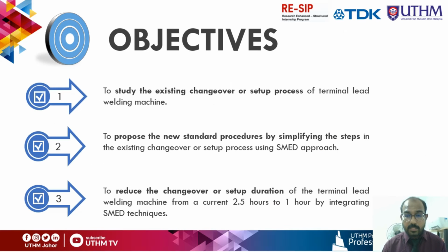The objective of my case study is to study the existing changeover or setup process of the terminal welding machine. My second objective is to propose a new standard procedure by simplifying the steps, the main activities that I showed before, especially in the existing changeover or setup process, using the SMED approach. The final objective is to reduce the changeover or setup duration from 2.5 hours to 1 hour by applying SMED techniques.